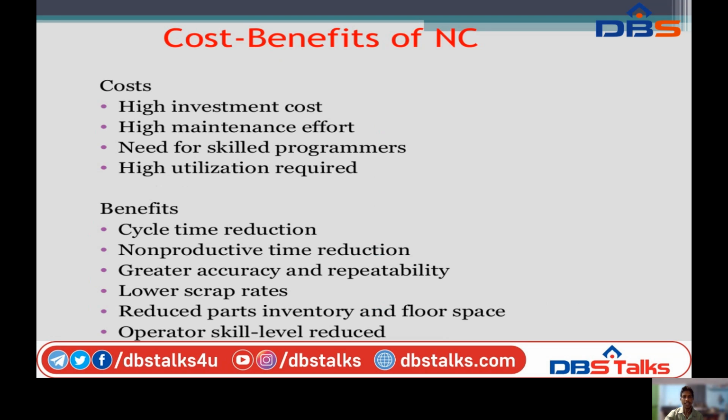Cost benefits of numerical control. Starting with cost: high investment cost, high maintenance effort, need for skilled programmers, high utilization required. When it comes to cost in particular, high investment cost. Why?